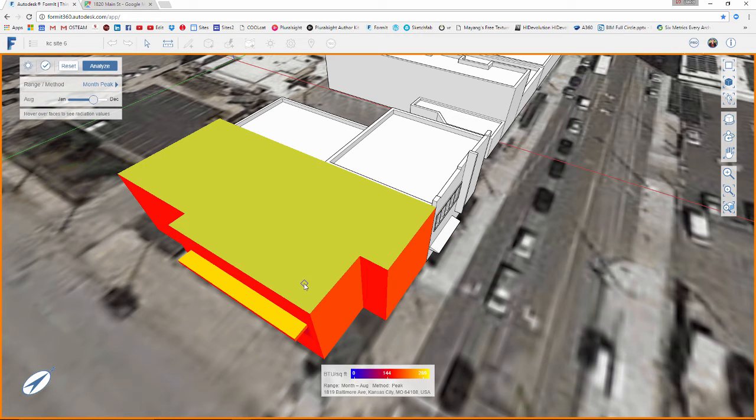And we have the heat equivalent of about one 100-watt light bulb, which is enough to burn your hands, every square foot across the surface of this roof. So we have pretty high intensity in terms of BTUs that we need to block, in terms of what kind of material we are using to reflect that solar radiation back up, in terms of the quality of that roofing system, and also that we're trying to block from coming into the building.